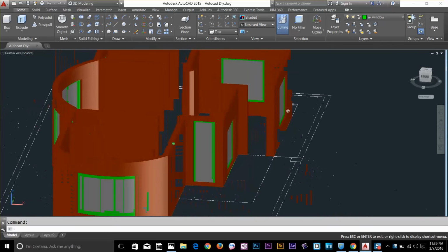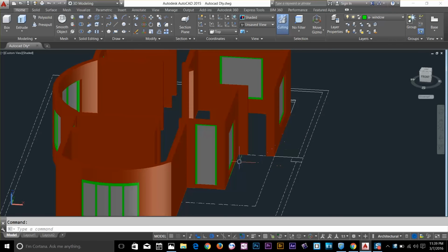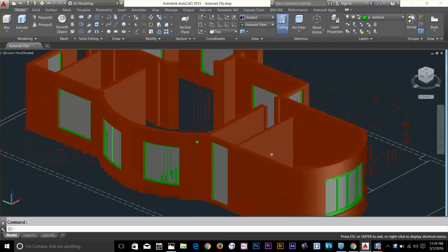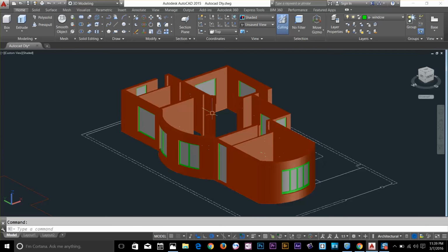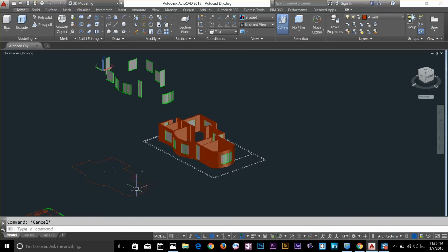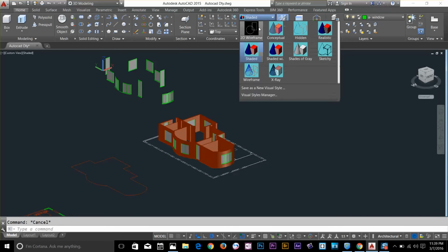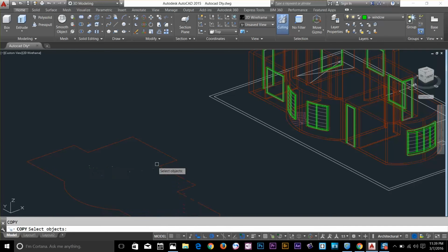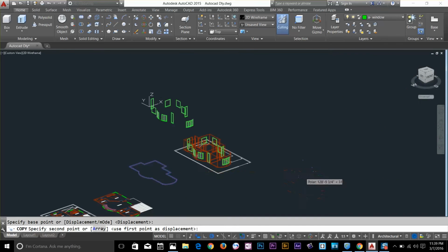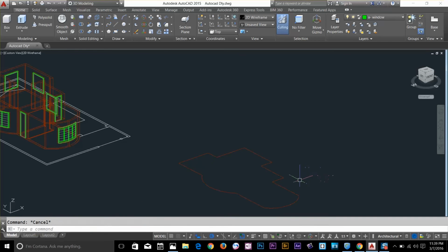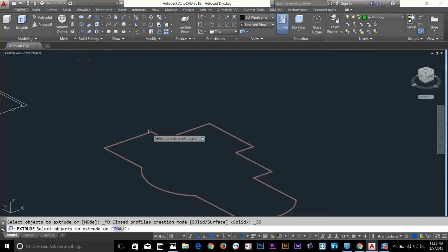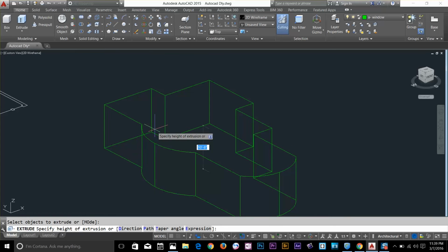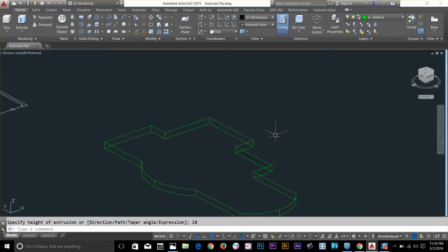So to make a door, what I'm going to do is, first of all, I'm going to make a slab for the bottom. So I'm gonna keep that building about 1.5 feet up. So I've got this outer mark here, so I can use that to make my slab for a ground. So I'll turn that, and then I'll copy this, and I'll just make one copy there, and then I will extrude this about, let's say 18 inch. Alright, so 18 inch, that's done.